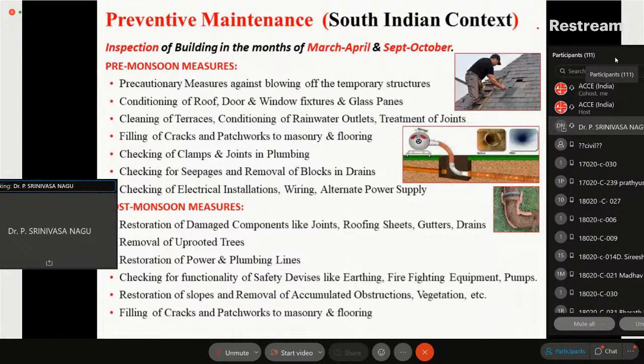When I was working in the Nalgonda Polytechnic as a HOD in 2002 or so, there were unprecedented rains. Our compound wall was acting like a dam. The water was full in the campus in the down conditions, and then there were openings in the compound wall, but they were closed by bushes. Nobody bothered about it. What happened? Those bushes stopped the debris, so the spillway was closed, and the water got built up, and it pushed the entire compound wall, and there was a big flood down.